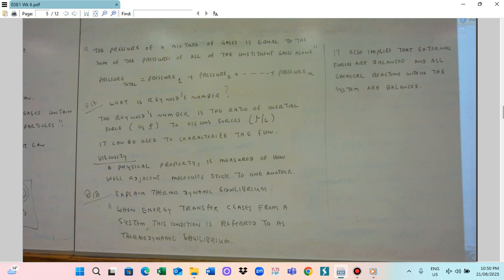So for the ideal gas and the perfect gas model, the equation PV equals nRT is stated for the ideal gas or the perfect gas. The ideal gas law implies, without restriction on the specific heat, that the compressibility factor Z is set to 1. It does not describe real gas effects, meaning the compressibility effect and variable heat capacity, van der Waals force, non-equilibrium thermodynamic effects, issues with molecular association, and elemental reaction with variable composition.